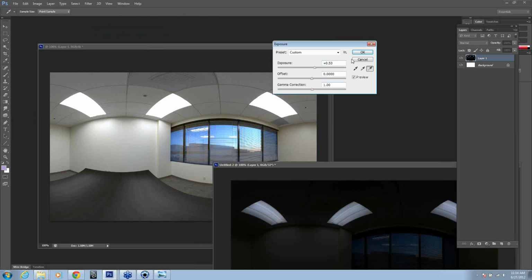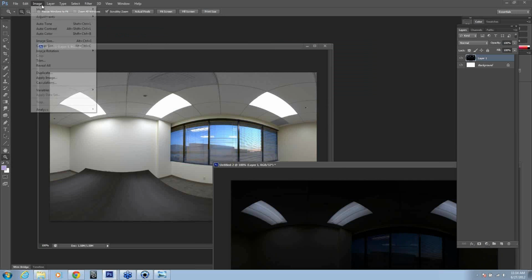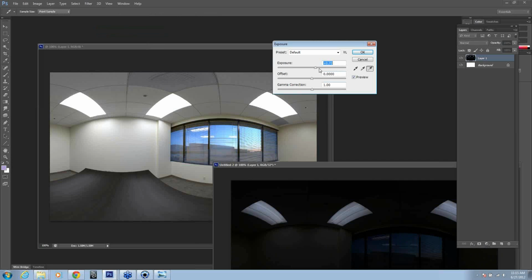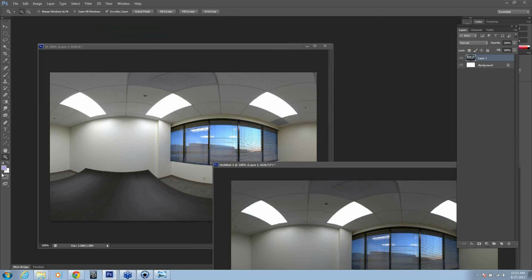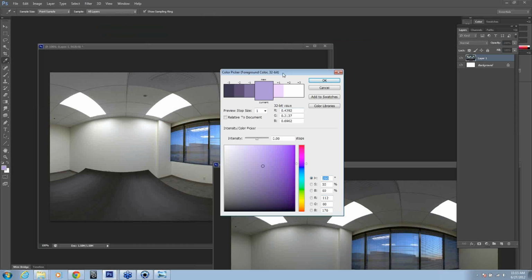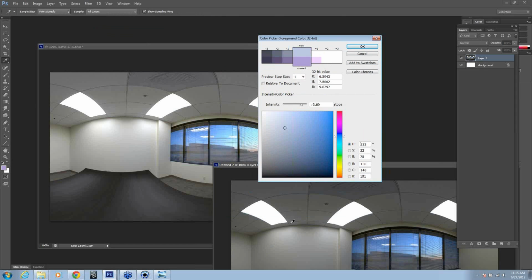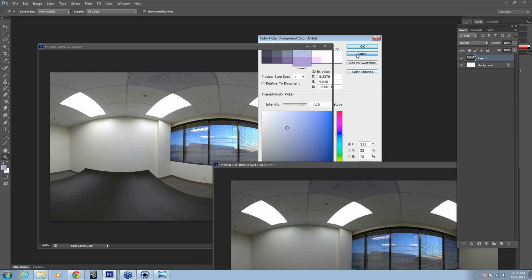And if you look at the color picker when using this, you'll see that 32-bit scale. And the reason this is important for doing product rendering for marketing is if you render an image out that's overexposed or underexposed, you can always pull detail back in your highlights and shadows. If you look here, you can see that because this is a light source, it's actually quite a bit brighter than the other pixels surrounding it. So it's brighter than just pure white.